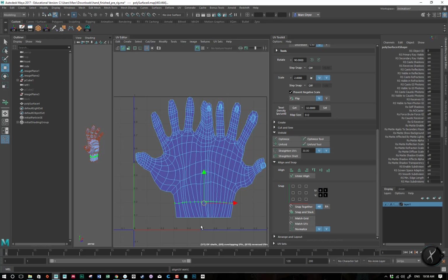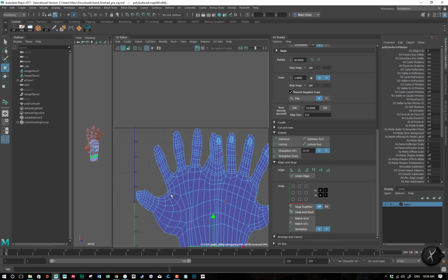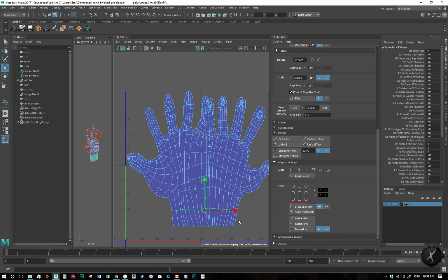So everything has to fit within the 0 to 1 UV space. You want no overlaps. You want to have minimal distortion. The lowest number of seams possible. And you could argue that, well, maybe I can keep sewing. If I kept sewing like this edge to this edge and this edge, and I could sew the edges of these things together. But then essentially you're making the 3D model again. So at some point you just have to leave it laid out like a flat shape.